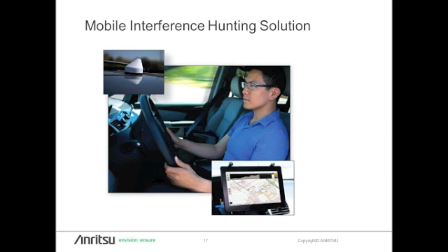So that's really the heart of the system: the antenna, spectrum analyzer, and tablet, and the software that runs both, some of the firmware in the analyzer and the software that runs in the tablet, to provide an elegant solution to deal with your interference issues from identification to approximate localization to the actual pinpointing of the interferer. It's one system that does all these things.